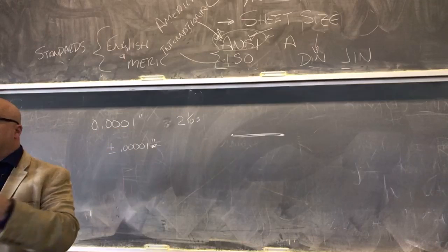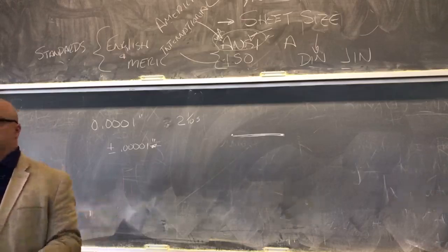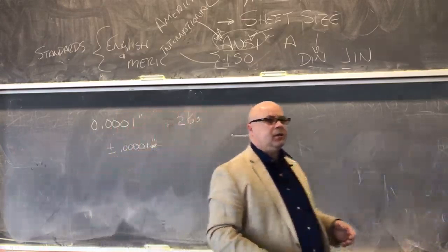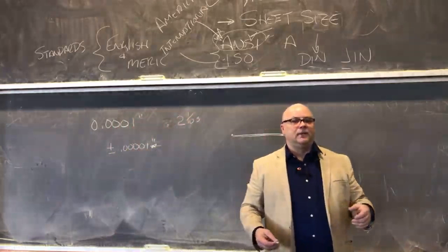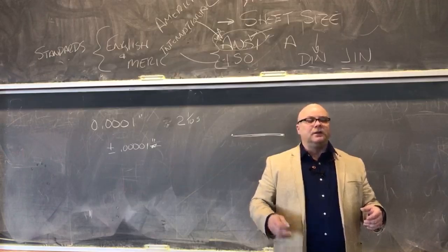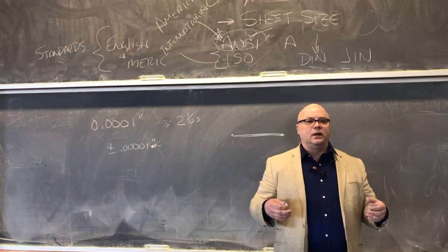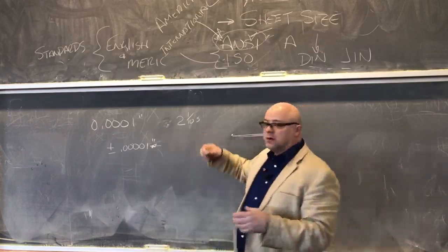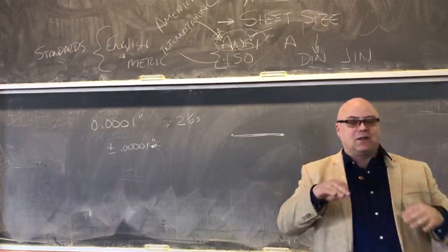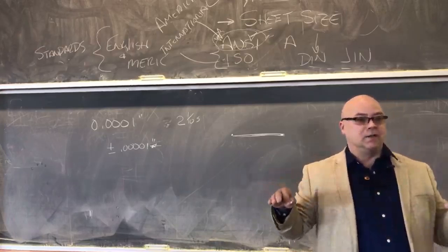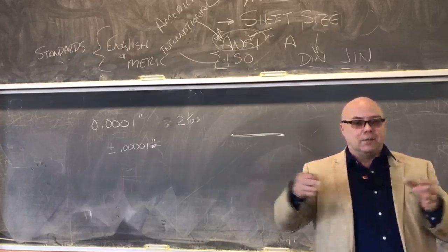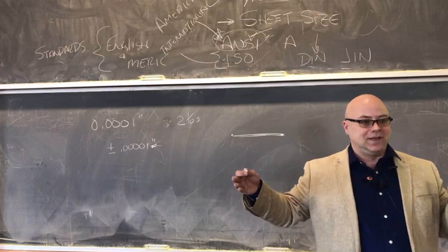And for the things that are important, what should we do with the tolerances? There's a few ways to call it out on the drawing. One way is to do this thing in the tolerance block where we do, if it has this many decimal places, it's this tolerance. If it has this many decimal places, it's that tolerance. So one thing, you could put more decimal places. In fact, if you put more decimal places on a drawing, it implies a tighter tolerance.